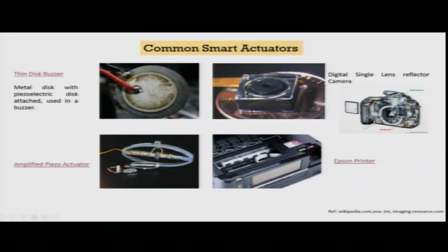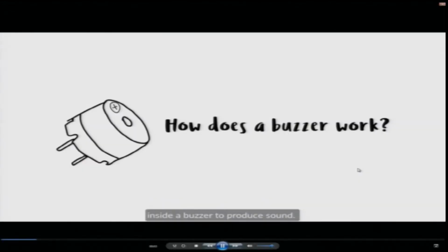Through this electrode you supply power to the piezoelectric disc, and by supplying variable current, you can actually deform this piezoelectric disc axially as well as circumferentially and radially, and once you do that, that vibration will generate vibration on this metallic disc. So, let us just see how this whole thing would work.